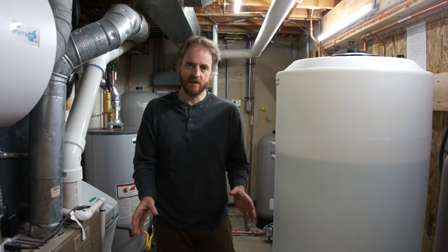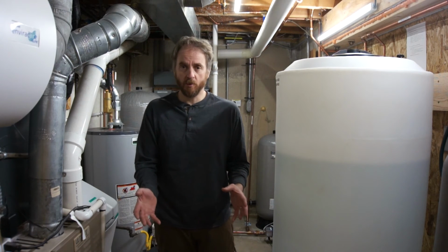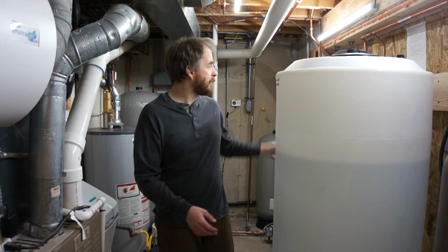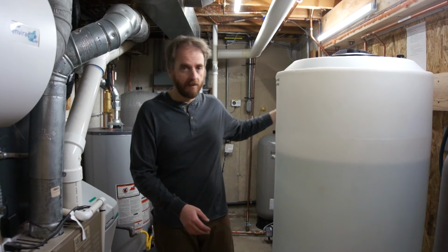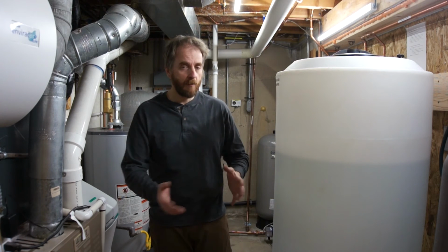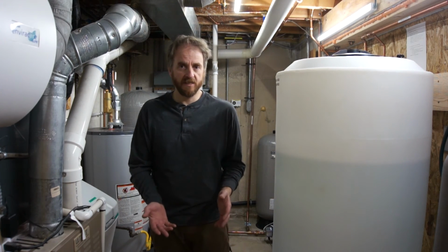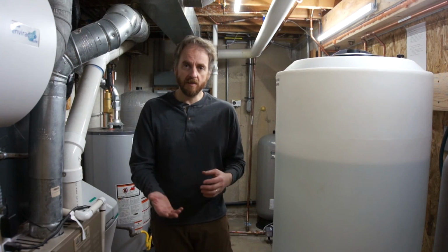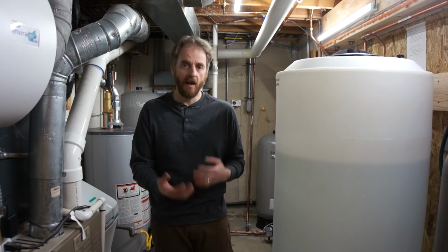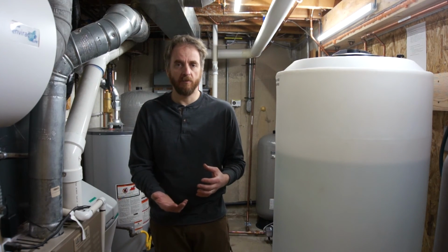We've been using this system now for more than 2 years. I built it back in January of 2020, and really the only things I've had to do are maintenance related. I replace the UV bulbs once a year. I weekly flush the RO membranes, and about every 6 months I change the filters. It has not been an expensive system to run. Now, I mentioned that the upfront cost of installing this thing was just absolutely insane, and that is the case, but once it's in, it's been a really easy system to live with.